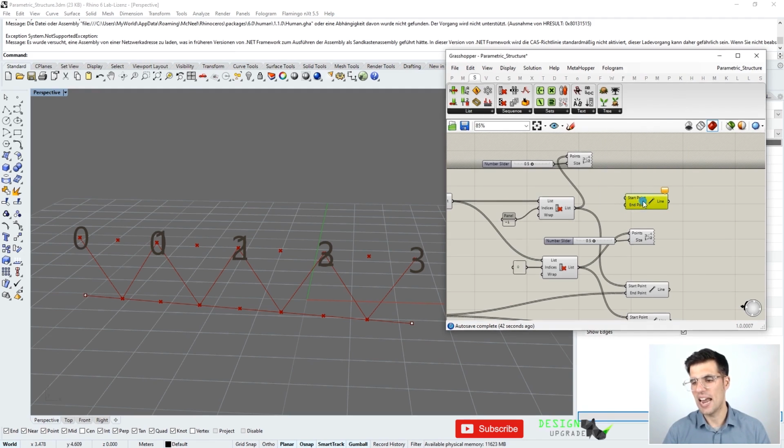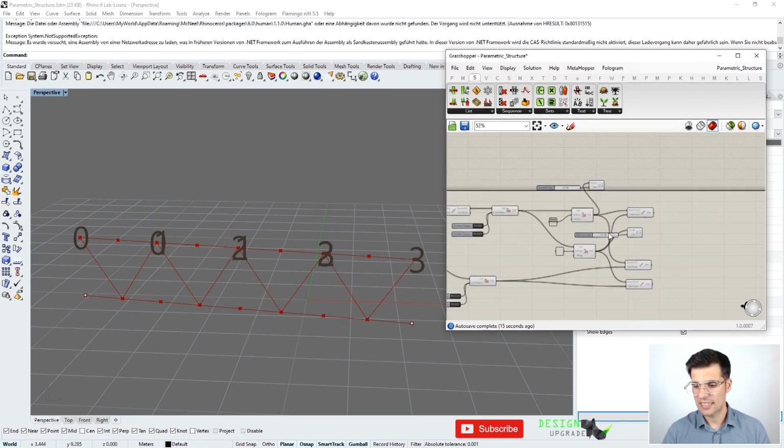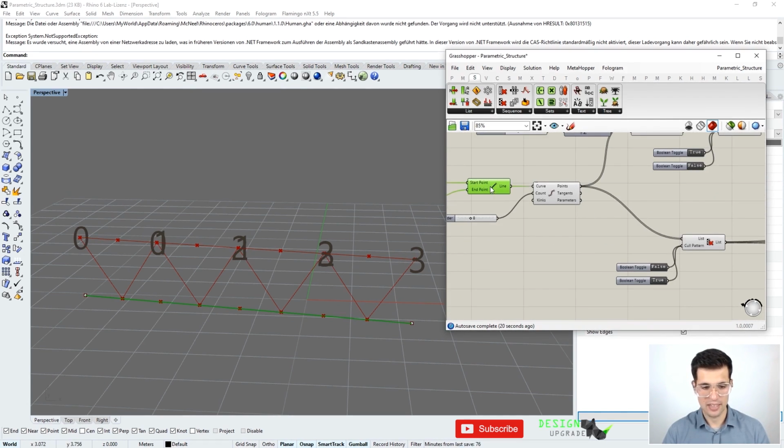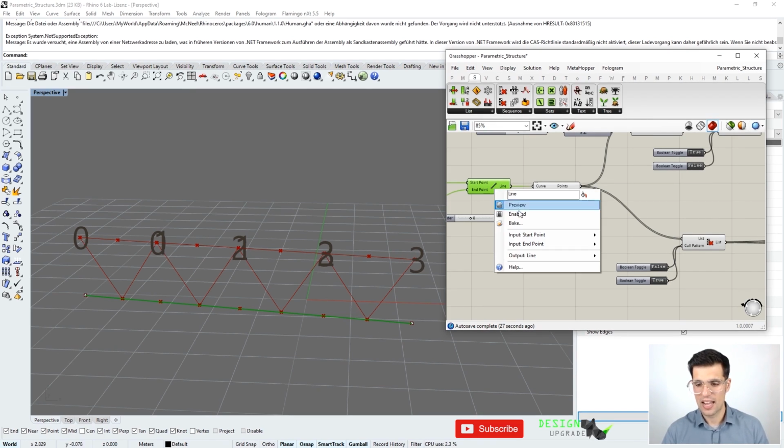So let's get the line component once again, and let's connect this first list with this other list. And yeah, that's right. If we take a look here, we can see how we are creating just four line objects, and these are lines in Grasshopper. So it seems like everything is working fine. And now let's move on to the lower chord. First of all, let me hide the original line that we used to divide and get our nodes here. So I'm going to hide it like that.